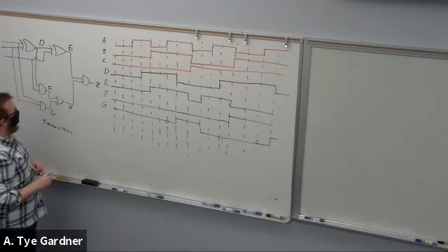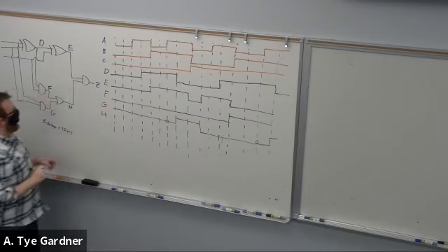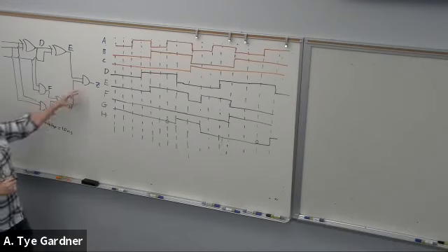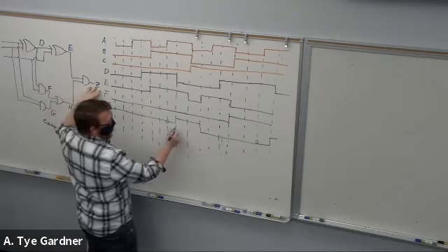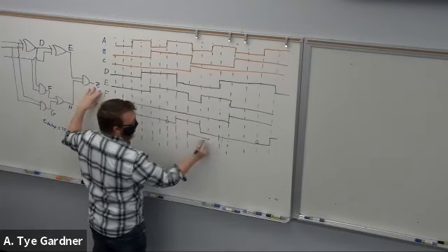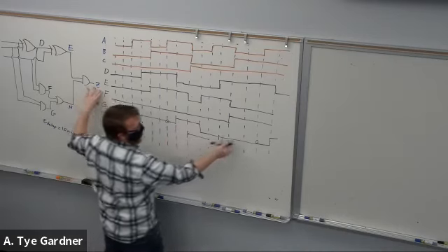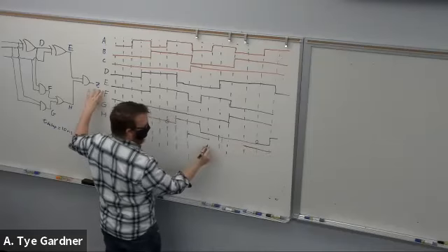H then. Well, H is an OR operation of F or G, so I only have to worry about these two. Just give the true with a 10 nanosecond delay. So there's a true here, shifted by 10 nanoseconds, and there's a true here, shifted by 10 nanoseconds.